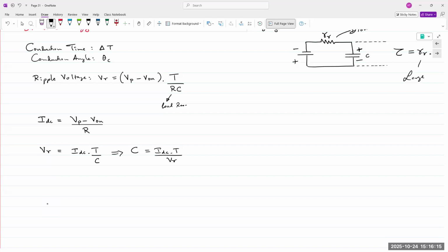For the most part, the ripple voltage actually does not matter, because to obtain a purely flat line, we would not simply just use a capacitor. We would actually take it and feed it into a Zener diode. So we'd have an absolutely flat line at the output. Okay. So you could have a ripple voltage of 1 volt, just randomly saying. But if your Zener diode is within that range, then it's going to cut everything out, give you a flat line at the output. Okay.